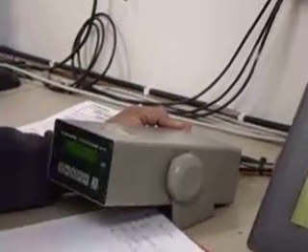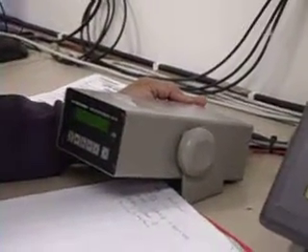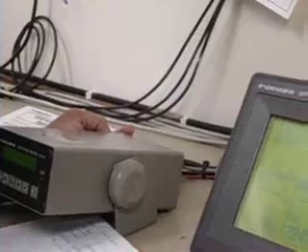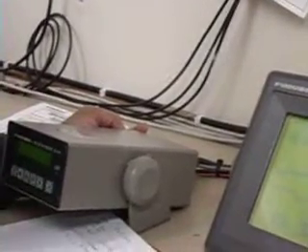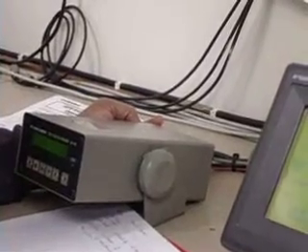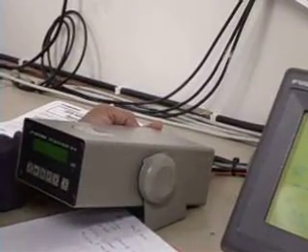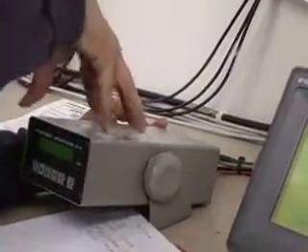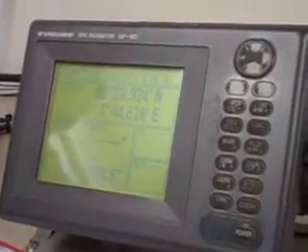So what happens on the coast? Every country has a station given in the ALRS Volume 2, which shows where the DGPS station is. They transmit the correction. Same, we are in Lowestoft, the Lowestoft station will transmit to the ship that for the Lowestoft area the correction is 0.2 minute northward and 0.03 minute eastward. The machine receives it, corrects it, and gives us a very good signal, within 5 meters correct.